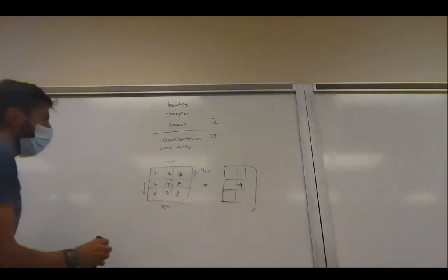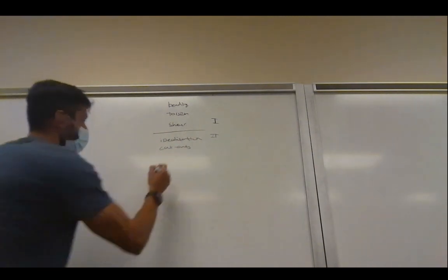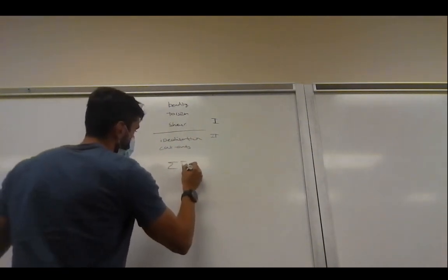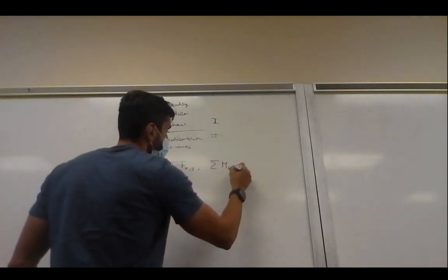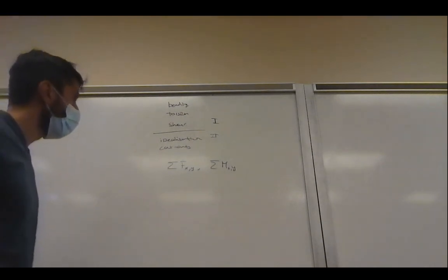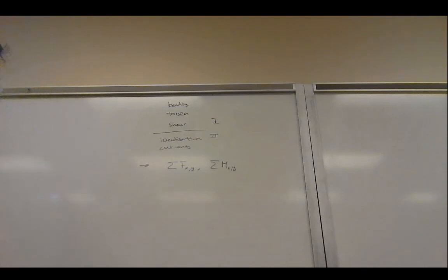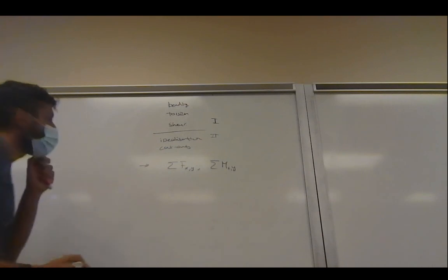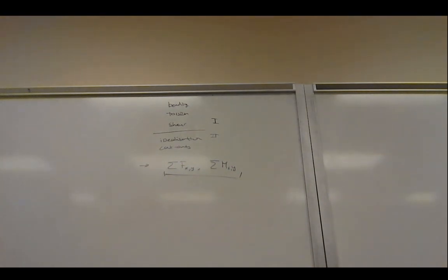And it seems complex, but at the end of the day, it often comes down to equilibrium of forces in x, y, and equilibrium of moments in x and y if we do a 2D problem. So even though you see a problem and it seems complex, especially in idealization, and unfortunately we did not properly record the last lecture, look at chapter 22 again, I think, and what you see just comes down to summation of forces in x and y most of the time.